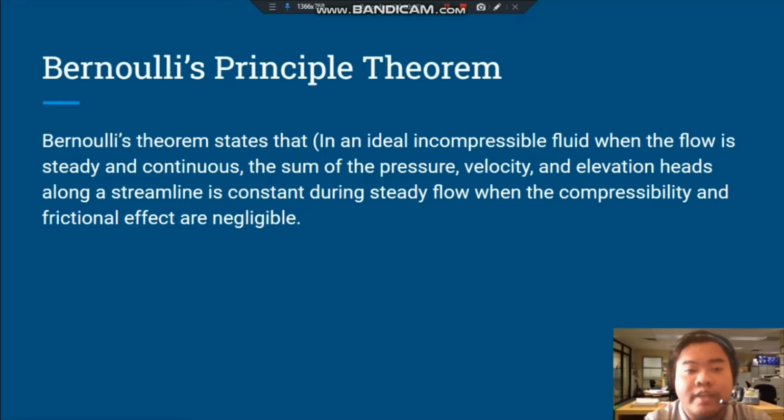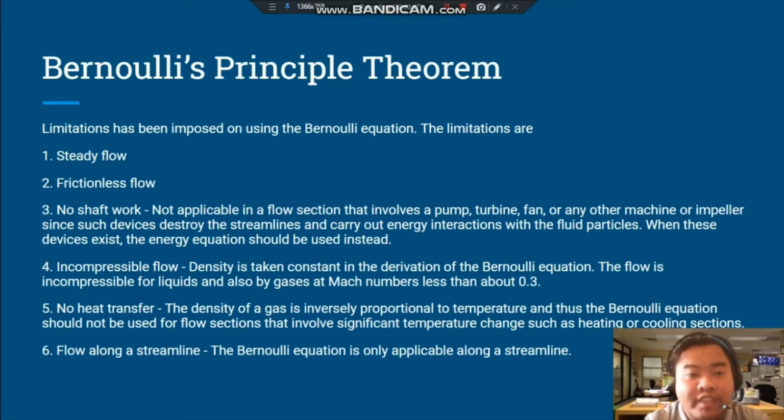Bernoulli's theorem states that in an ideal incompressible fluid, when the flow is steady and continuous, the sum of the pressure, velocity, and elevation heads along a streamline is constant during steady flow when the compressibility and frictional effects are negligible. There are some limitations that have been imposed on using Bernoulli's equation.